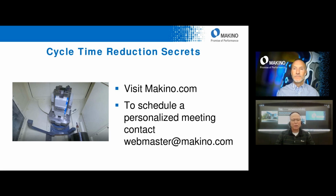Yeah, if your settings are incorrect and you've got a heavy weight but a quick accel and decel setting, eventually you'll get into an overload condition on the motor or the servo, and then if you continue that, like anything else, you could damage the machine. So you really want to measure that pallet before you get it in there and enable IAC.